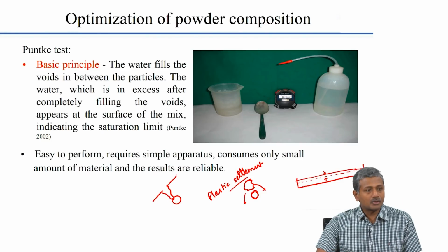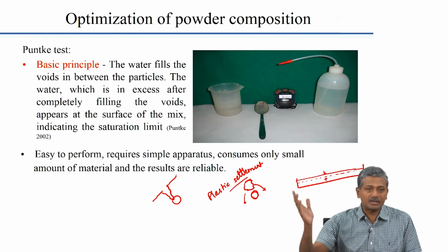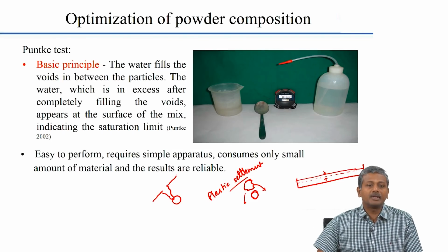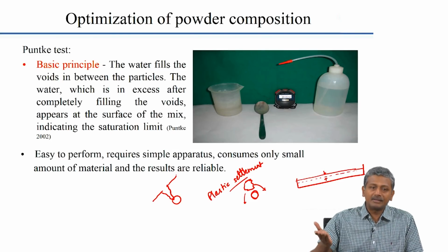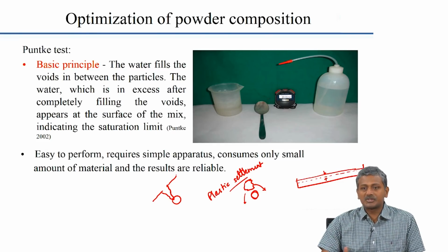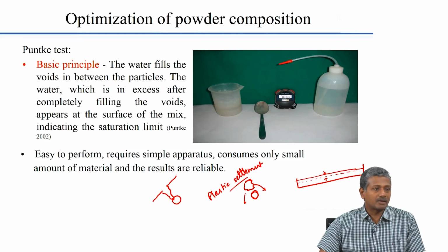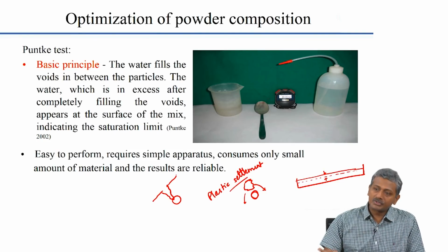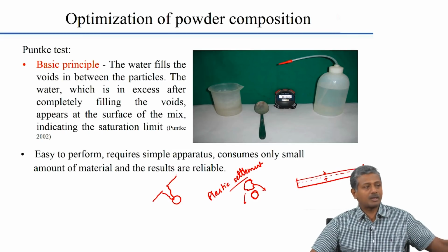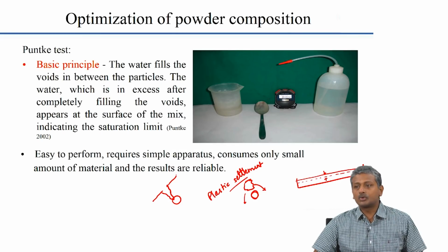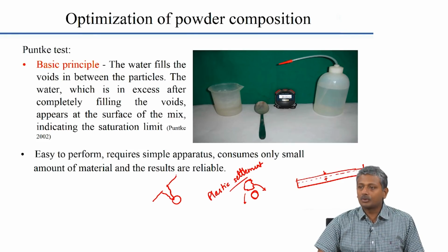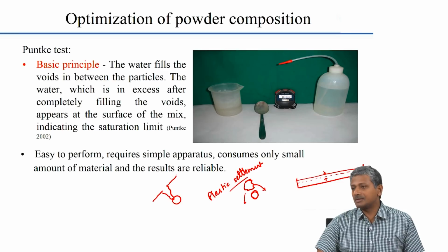Now, we saw this problem in some of the structures that were actually designed within IIT campus. You know, you have seen the engineering design building. The engineering design building had slabs laid with SCC on top, and these slabs we started seeing these problems of plastic settlement cracking. So, what we tried to do was, when we designed the same SCC for the slab that is right outside your library, which holds the chilling water plant for the air conditioning of the library, that slab we took precautions to ensure that we will not get this type of cracking.